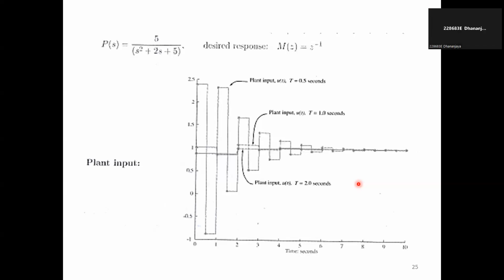Sir, will this system be an energy efficient one? Because it's always working, right? For it's not energy efficient. No, it's not the optimum control system. But when you say optimum control, usually you say minimum energy. This is not minimum energy, but this is optimal in a different sense, for time critical applications. You want to have the fastest time, the shortest time rather. So in that case, this is the way to go. Design a deadbeat controller. It's not energy efficient anyway.